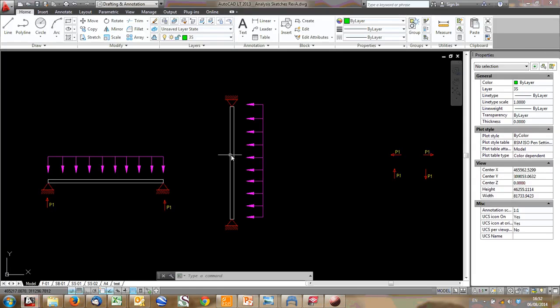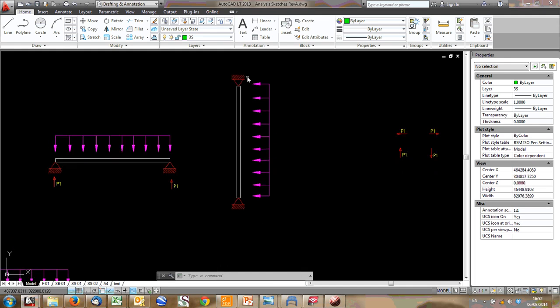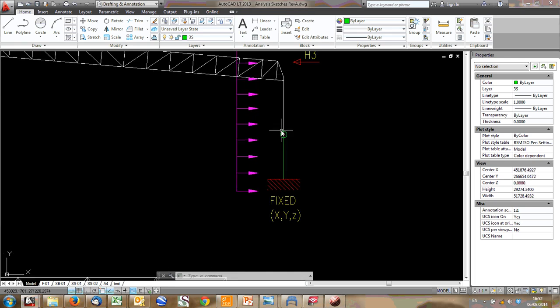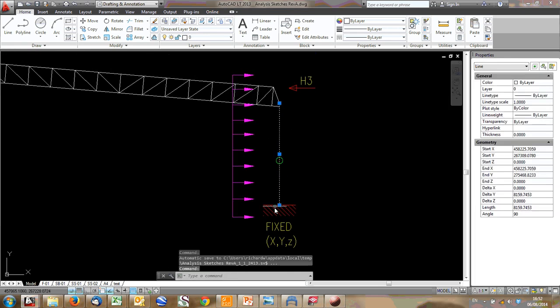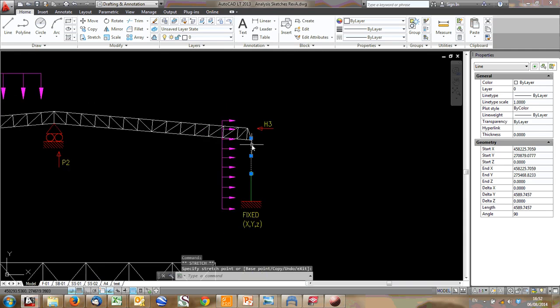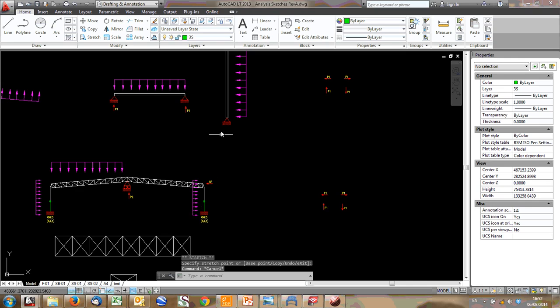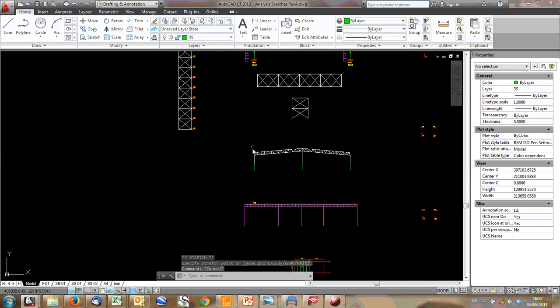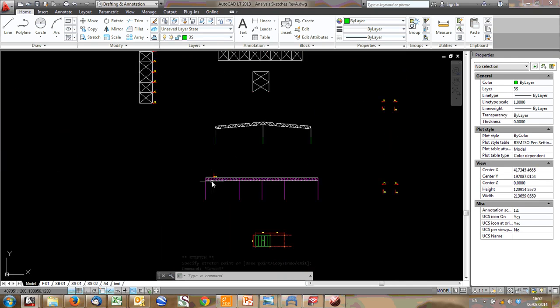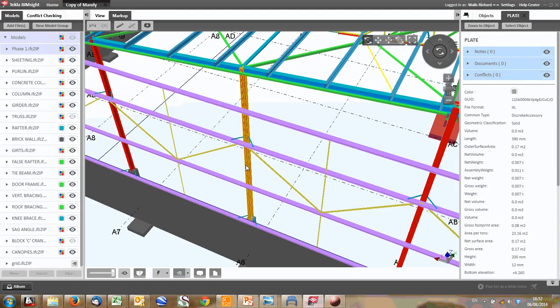Let's go back to our model. All right, we've analyzed our column. Once again, we've got reactions. How do we support these reactions? Well, the bottom one's quite easy. It sits that the model we've just looked at, the simply supported beam, is this section here. Well, sorry, it's actually not on this face, but it's on the other face. It's on this face along the gable edge. This column here, going up, going down.